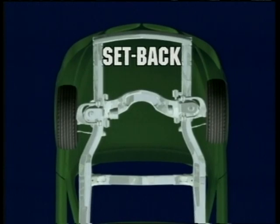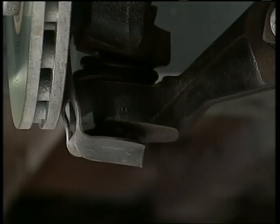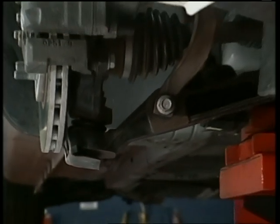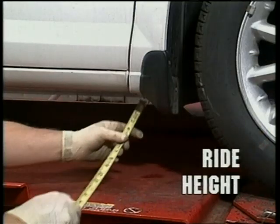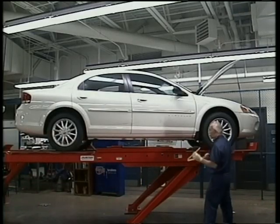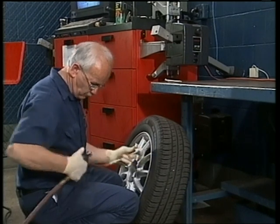Setback is a condition in which one front wheel is moved back so that there's an unequal wheelbase between the left and right sides of the vehicle. Setback may be caused by impact to a front wheel assembly that moves a control arm, engine cradle, or suspension rod backwards. Ride height is simply a measurement from a level surface to a predetermined point on the wheel or suspension.